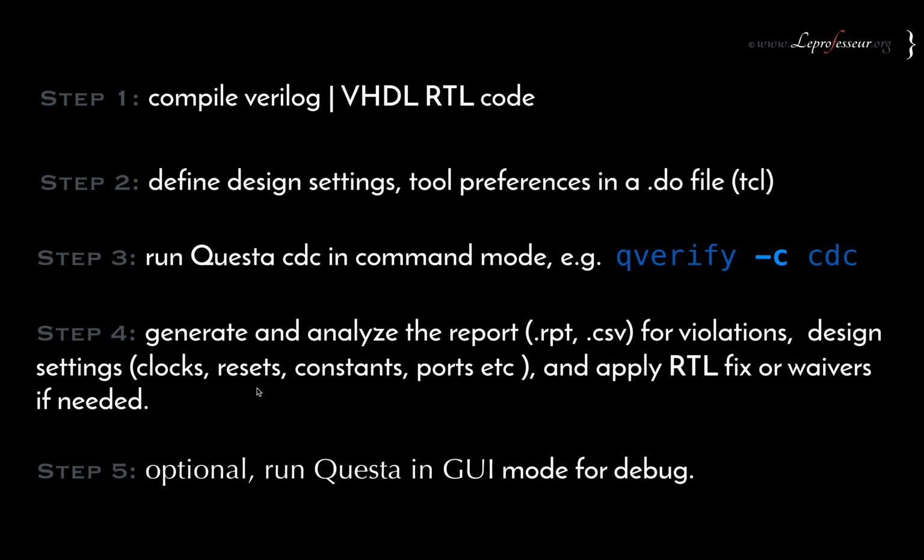And if you are satisfied, you are good. If you are not satisfied and you want further debugging, you can invoke the GUI mode for the Questa CDC. How to invoke the GUI mode? Simply launch the qverify command. Qverify.